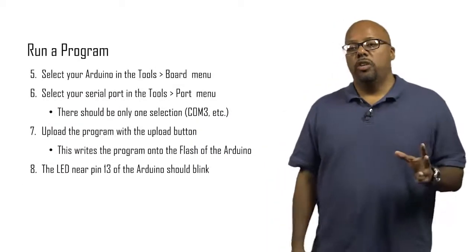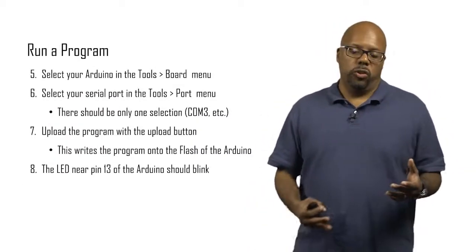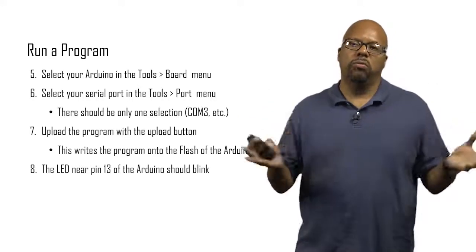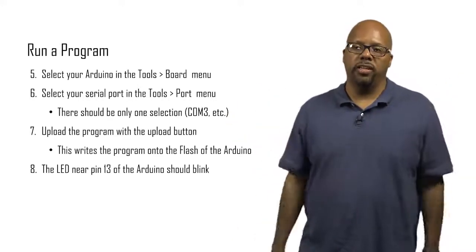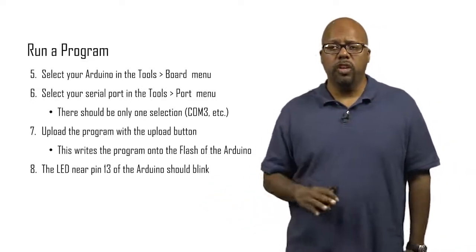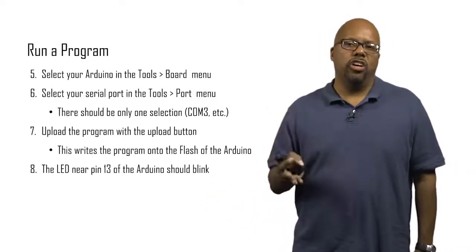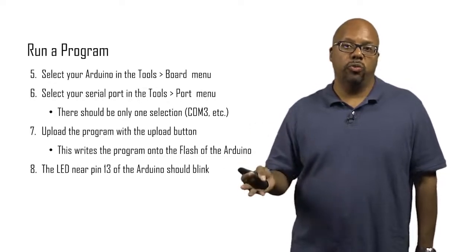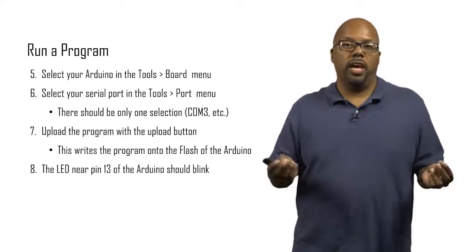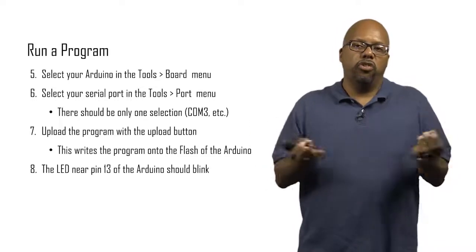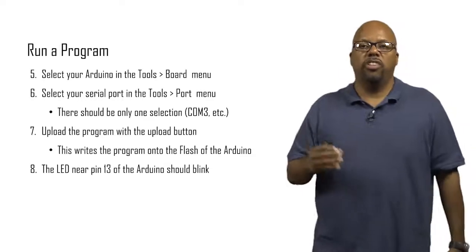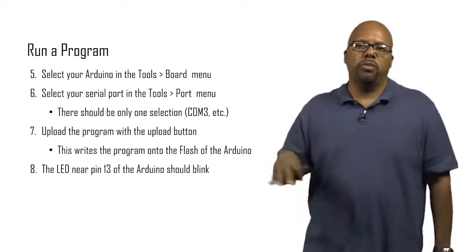Your goal is going to be to run that program, and what it should do is make an LED blink on the Arduino. Then you know my setup is working correctly. To get to the point where you run the code, first you want to make sure that the machine has recognized your Arduino correctly. This you may not have to do. If you're lucky, as soon as you plug it in, your OS will detect it and everything will be fine. But here are some checks that you typically do before you actually program.